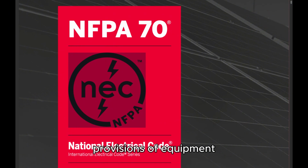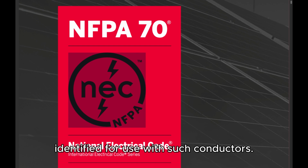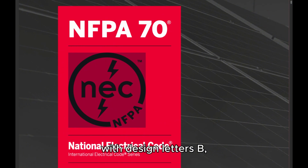1. Termination provisions of equipment for circuits rated 100 amperes or less, or marked for 14 AWG through 1 AWG conductors, shall be used only for one of the following. 1, conductors rated 60°C (140°F). 2, conductors with higher temperature ratings, provided the ampacity of such conductors is determined based on the 60°C (140°F) ampacity of the conductor size used. 3, conductors with higher temperature ratings if the equipment is listed and identified for use with such conductors. 4, for motors marked with design letters B, C, or D, conductors having an insulation rating of 75°C (167°F) or higher shall be permitted to be used, provided the ampacity of such conductors does not exceed the 75°C (167°F) ampacity.